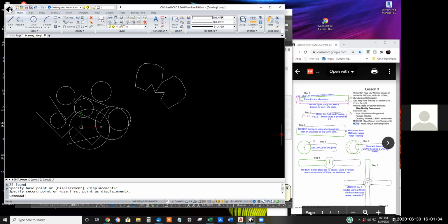It came out pretty weak on the handout, but right here it says start here in the upper left corner. We're going to go down, across, and up, and then close to get this, I think you call that a trapezoid. And then we'll erase this bottom line because we don't need it when we reflect the half blade to make a full wing using the mirror command.